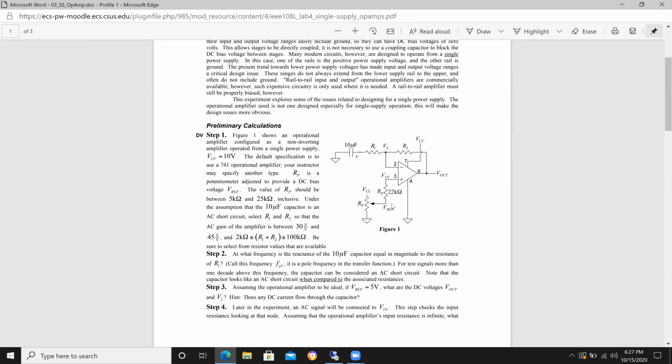But what it means by mid-band is, hopefully you're familiar with what the pass band chart looks like for a bandpass filter. It's going to reject signals, say from DC up to a kilohertz, right? Then it's going to pass signals from a kilohertz to 100 kilohertz. Then it's going to reject signals above 100 kilohertz. That's what this op amp is doing, the way this gain stage is set up. Not those frequency values, but in terms of plot behavior, that's what it's doing. Why is it doing that?